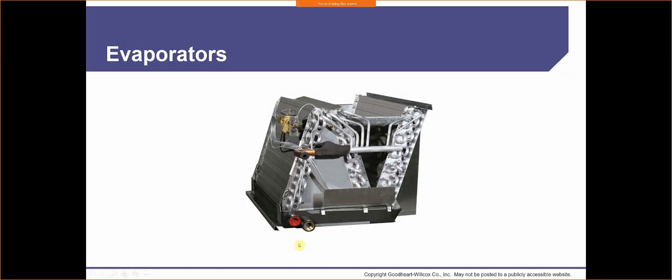The reason we have two little holes here, couple reasons. If my condensate drain gets plugged up for whatever reason with this hole, I've got a backup. I can have another line for my condensate that connects to here. So as my water level fills, if my primary doesn't drain, well, my secondary should take over that load.